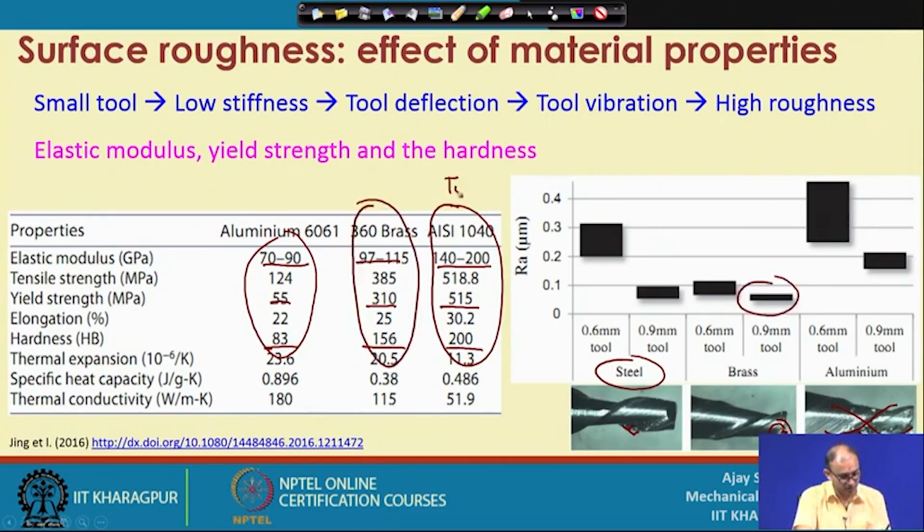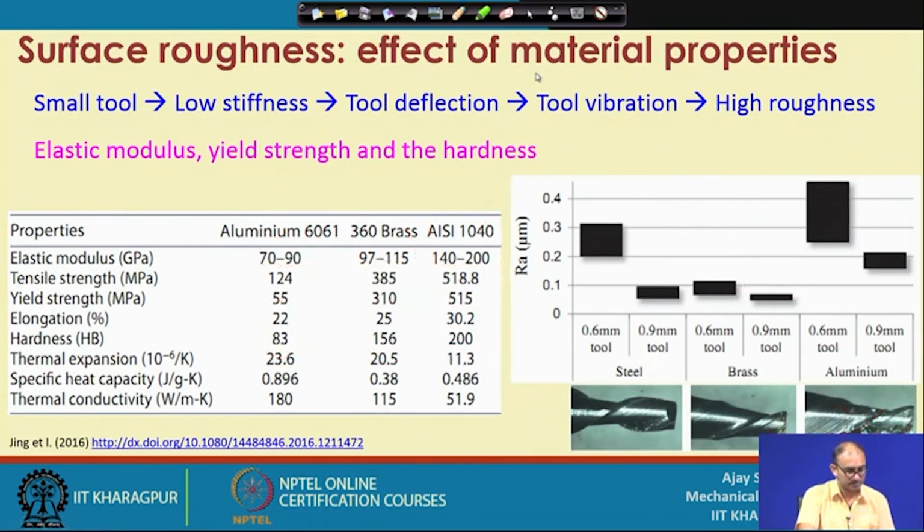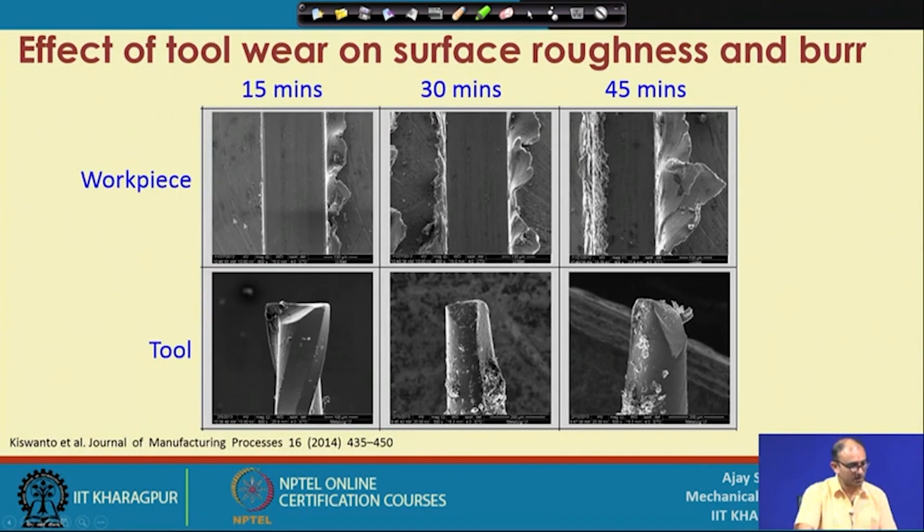So, here the tool wear is a problem, and here material removal is a problem, correct. So, this way, because anyhow you have to cut the aluminum, but you have to finalize the process parameters in such a way that you do not end up with this. You use some type of mist coolant and you add some type of projector with a high pressure, so that it will remove these things very easily, right. So, here it is the tool wear.